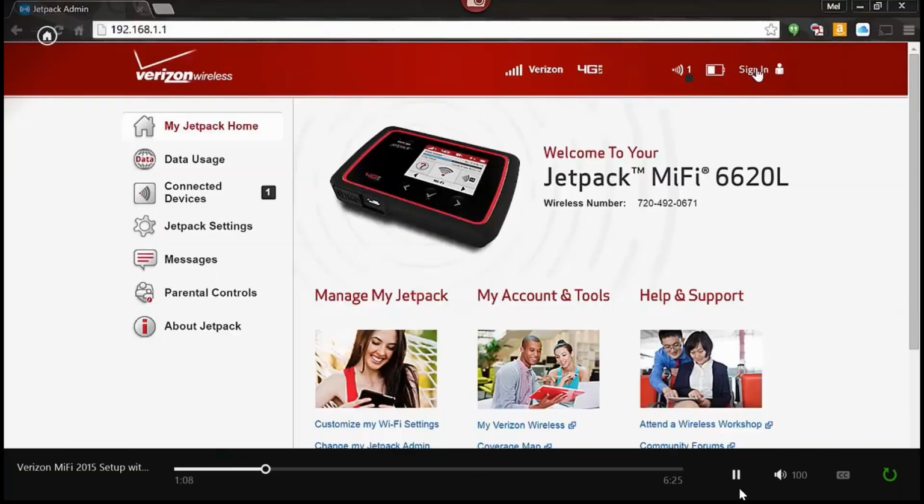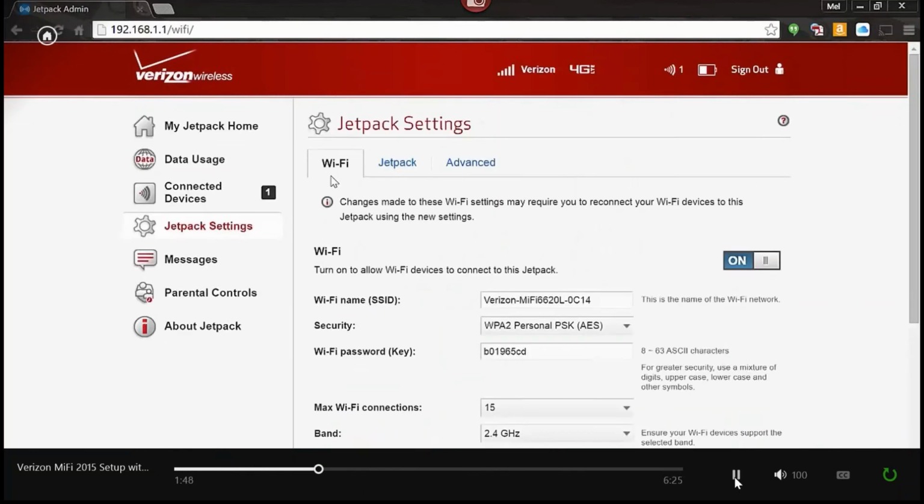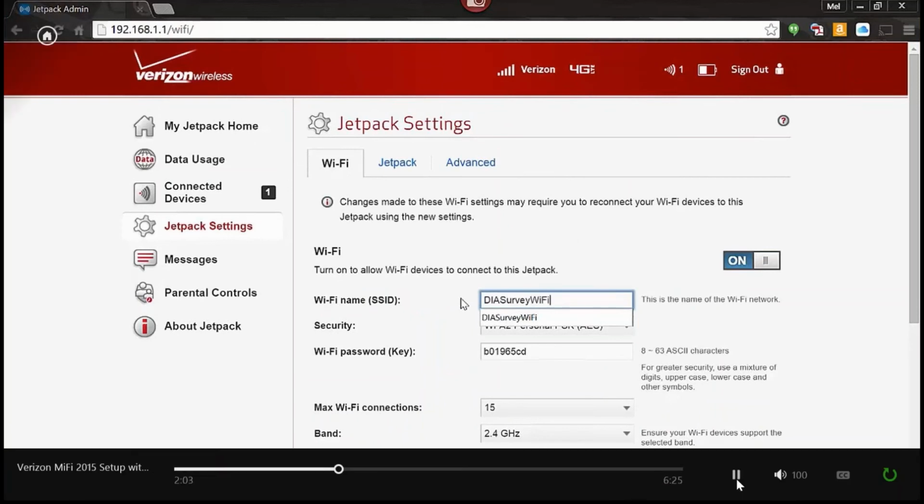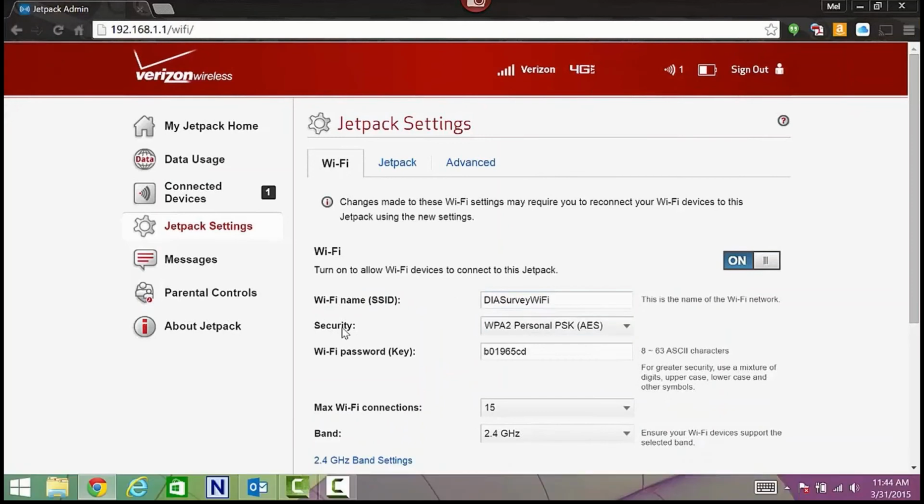So in areas where you're not getting great data service, pay attention to that little icon and see if you're getting a base data age outside the recommended 1 to 2 seconds. That could definitely be why you're losing a fix, or it could also affect your precision as you're measuring. The same thing holds true if you are using a base station and a base radio. So pay attention to that.